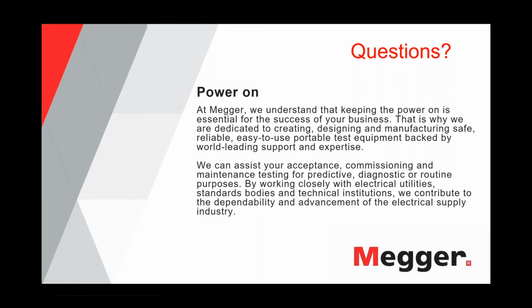So for a commissioning test, 10 delta is typically not necessary or not recommended. And we even see cases now where it is actually kind of confusing customers because, and Henning can comment on this much better than I do because he has a doctorate in chemistry, the cables still undergo changes in their insulation properties when they're new.